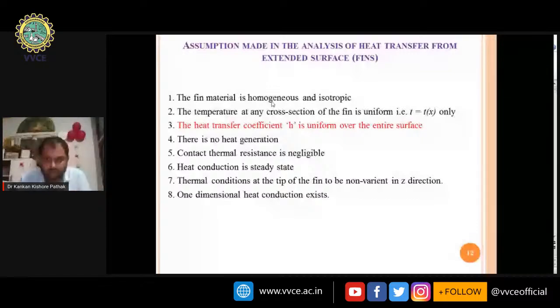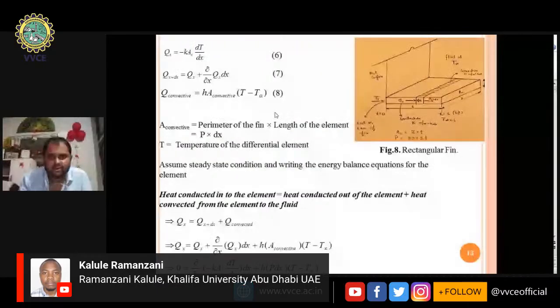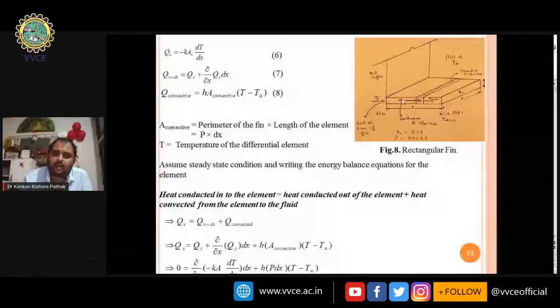Now, I am just giving a short description of this. So, how to analyze the extended surface analytically? Suppose we have a pin and a base surface, and we have a rectangular fin here. In the solid part, we always have to consider conduction, and we take an elemental area of a rectangular strip. We are considering dx as the thickness of that strip, and we can say that qx amount of heat is entering here, and q(x+dx) is leaving that element.